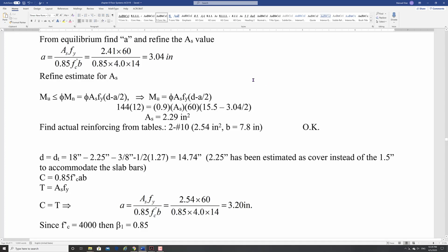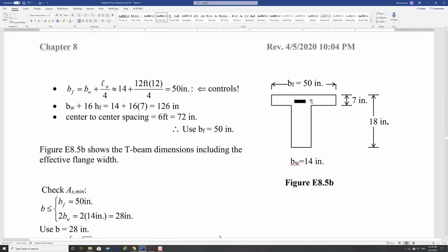But you're going to put your bars here, right? So these are your beam bars. And this is your slab. But your slab already has bars, right? Your slab has bars that are going in this direction, right? That's your longitudinal steel, right? Going that way,